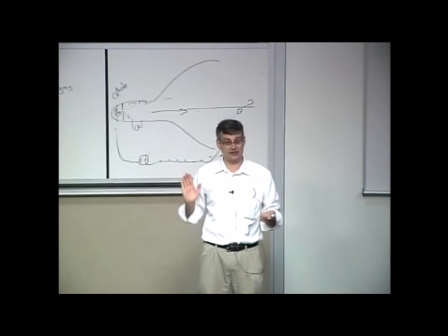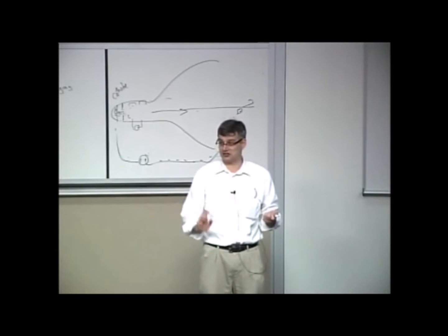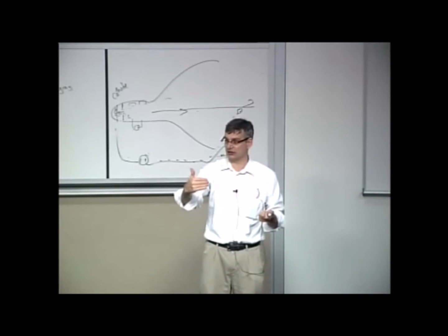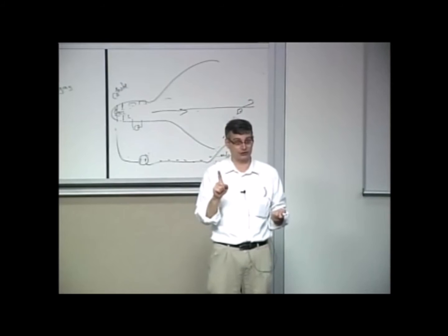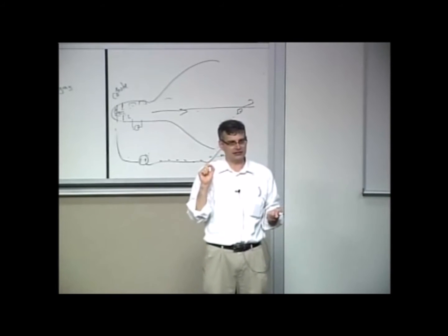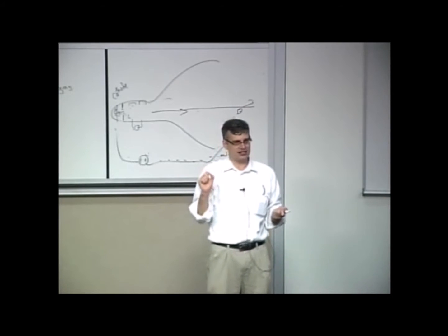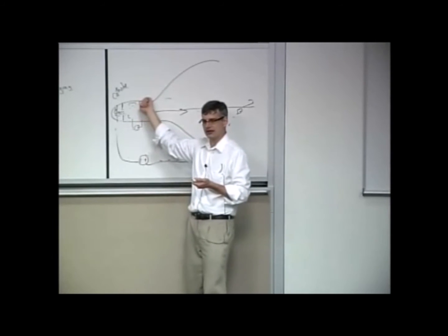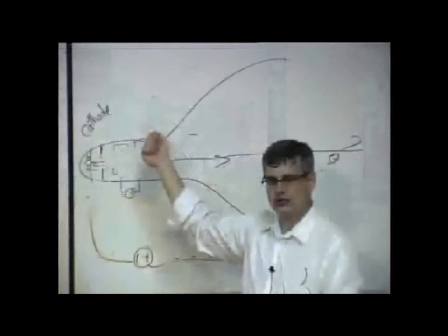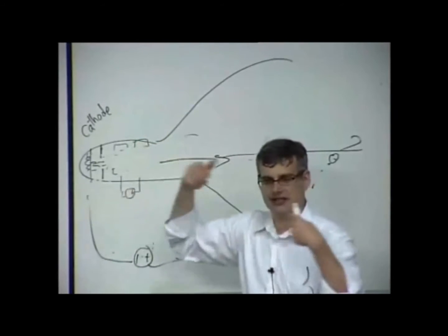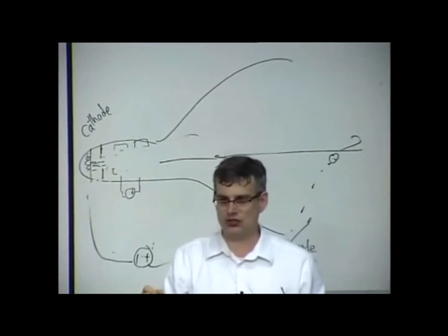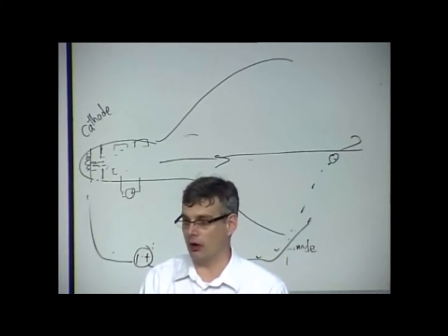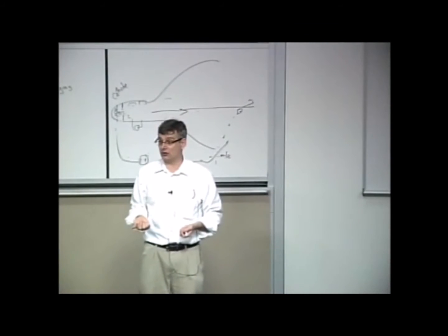You turn it on, you let it go for a long time. That 1/50th of a pound, if exerted continuously for days or even weeks, will integrate to a very large acceleration. And what's more, you achieve that acceleration with relatively little fuel. Because in this case, the fuel, the thing that you make the positive ions with, is really only used as the momentum, as the propellant. It's not actually being used as a source of energy. In the rocket, the fuel has to do both. And therefore, that limits your options.